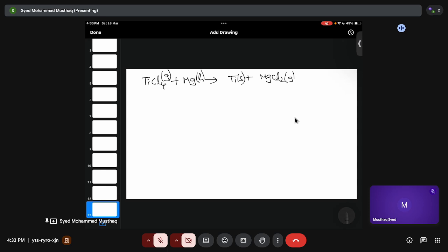There is a gap between the melting point and boiling point, because we are using liquid metal. In this region you have magnesium as liquid. Above this region, the magnesium is vapor, and the vapor-vapor reaction is tricky and not as efficient compared to the liquid-gas interaction.